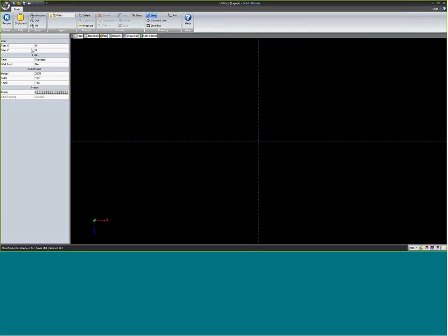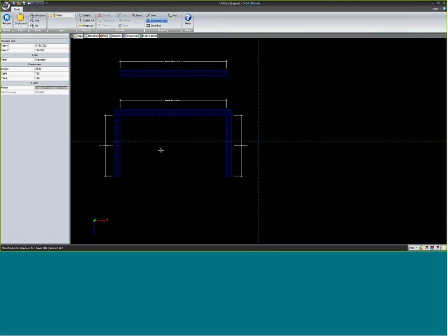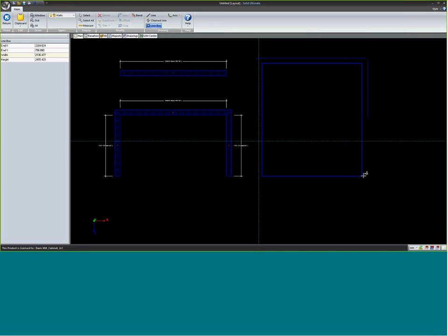In your wall drawing, I need to cover each of these little groups up here kind of independently. We're going to start over here and work our way back. Most of it is pretty self-explanatory. Line is just to draw an individual wall, and it lets go at the end. A chained line has multiple walls and continues being attached every time I draw a wall. At the end, I've still got this tail sticking here, so I can just tap my escape button to let go of that wall. A line box is just what it says.